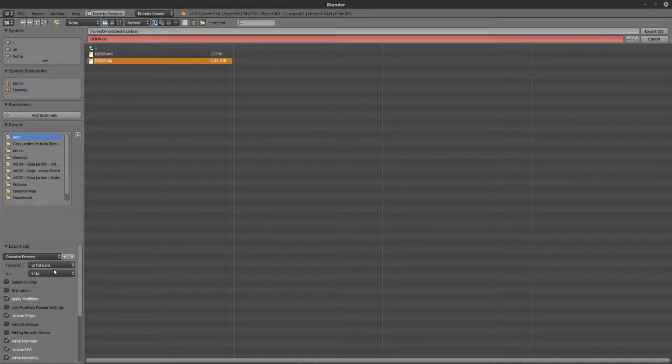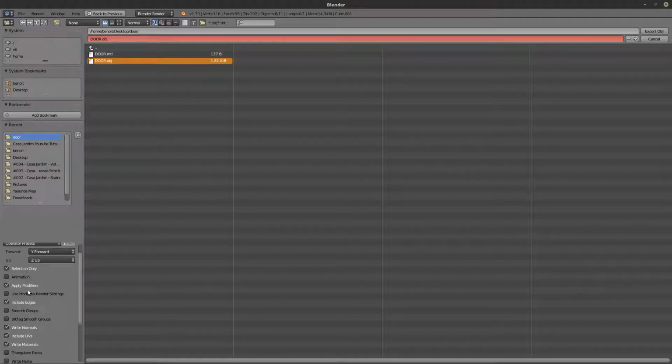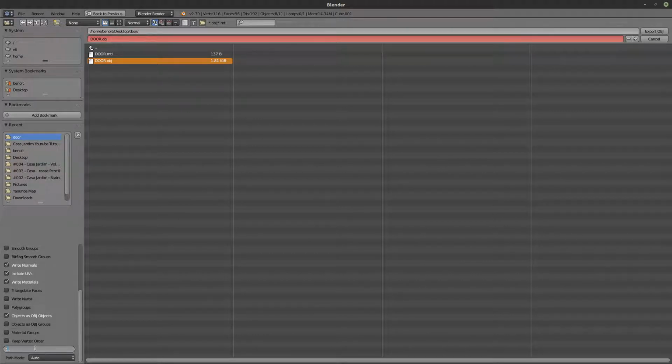Let's save that. Make sure that my up is Z up and Y forward, selection only, and the scale is set to 1000. Okay.